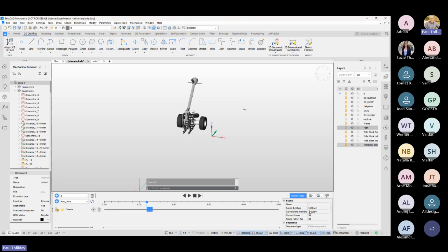And on the right hand side, we've now got the properties box, and we can change our camera position and target. So at the moment, we're going to say our camera position is fixed. And the point I want to fix it to, you go to the plus icon there, and it says select new path. And then we're going to simply select on the work point that we just created and click OK. Let's join that there. So that gives our position for the camera.